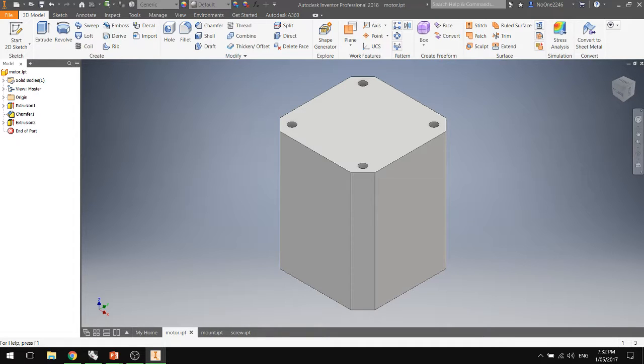Okay. Oh, nice. It's up to you if you want to put the thread in or not. Would I then put the thread in that model? You can put a thread in that way, it's not going to matter. It's only if you have a screw and you want to send that to the manufacturer to get a screw made, then you as an engineer would put a thread in. Otherwise I'll just make a plain screw. But I need that threaded, right? If you want to make sure the screw fits, then you would thread that. Is it the same process of running the thread on the screw? You split the cylinder, and you specify what type of thread you want on there. Cool.